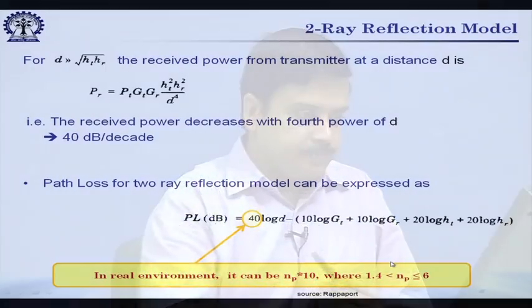What we have seen in the previous lecture is the path loss, or the signal attenuation due to separation between transmitter and receiver. What we have said is the average received signal strength at the receiver is inversely proportional to the separation distance raised to the power of a certain exponent, and that is the last expression as we have seen.